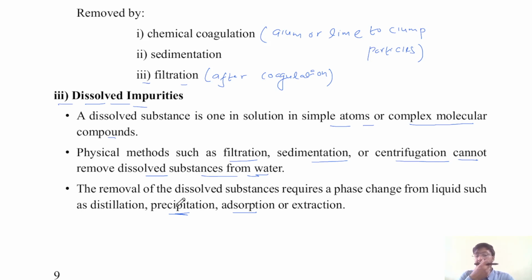Sand, clay, and algae are examples of suspended particles. Organic colorants are colloidal particles. Salt minerals are dissolved particles. Suspended particles give turbidity and color to water, and colloidal particles directly affect the water. They create color, odor, and taste in water.